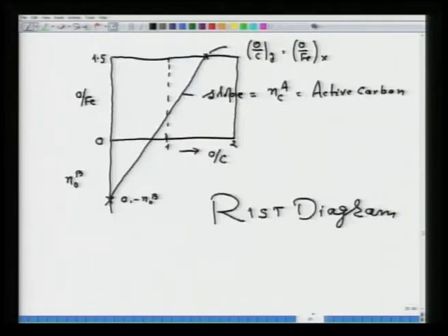Remember, we started with the pure liquid iron, pure Fe2O3. Now, with this addition we have come closer to what is happening in actual blast furnace iron making. We brought SiO2 of the gangue into the picture, we brought MnO2 of the gangue part of the ore into the picture, we made liquid iron and we added silicon, manganese and carbon. So, heat demand can always be updated according to the actual situation. Now, after understanding this, we can modify the material balance equation to incorporate the heat balance equation also.